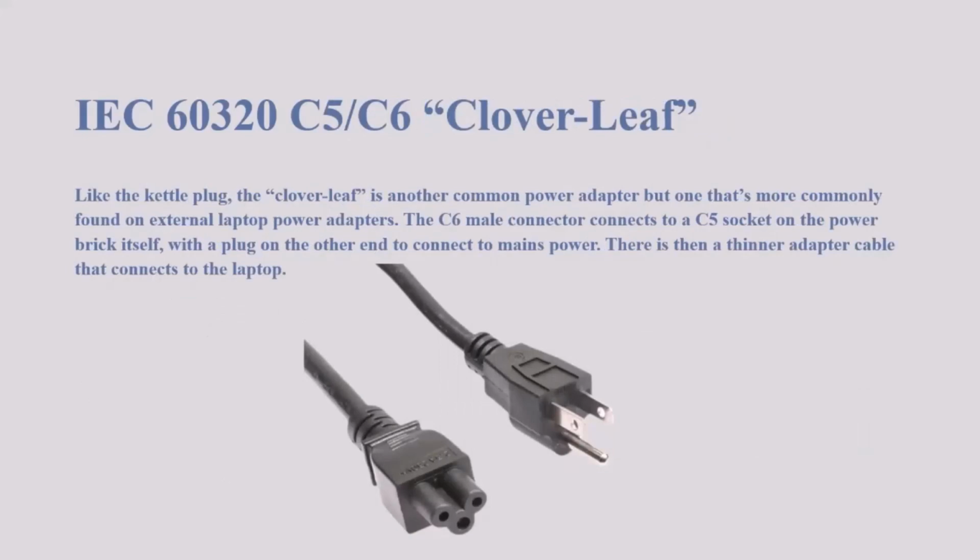IEC 60320 C5 and C6, the cloverleaf. Like the kettle plug, the cloverleaf is another common power adapter, but one that's more commonly found on external laptop power adapters. The C6 male connector connects it to a C5 socket on the power brick itself, with a plug on the other end to connect to main power. There is a thinner adapter cable that connects to the laptop.